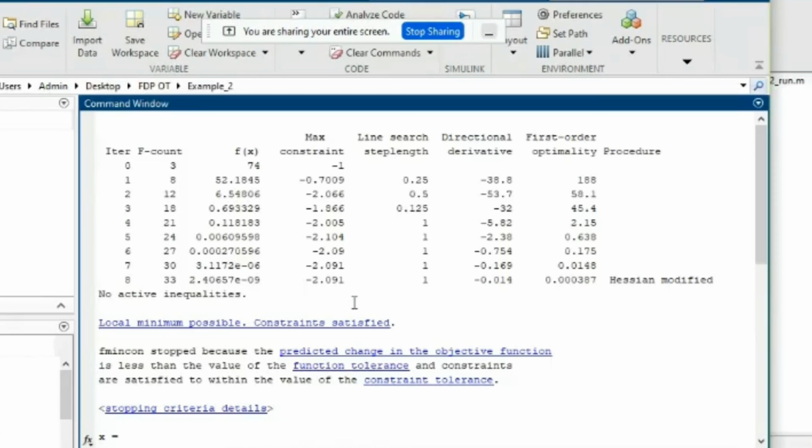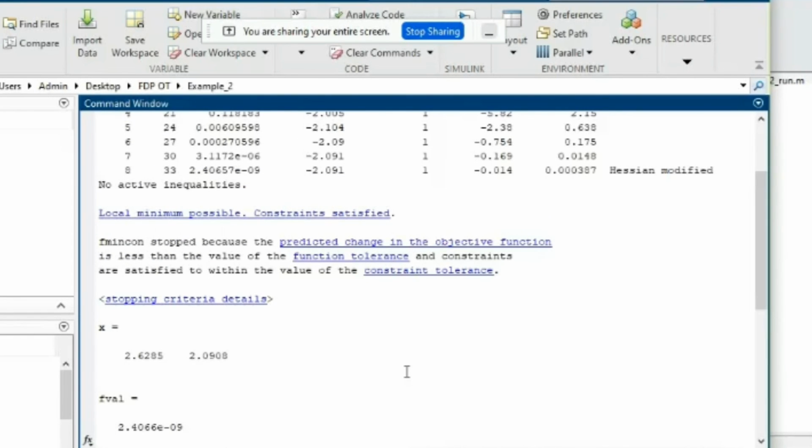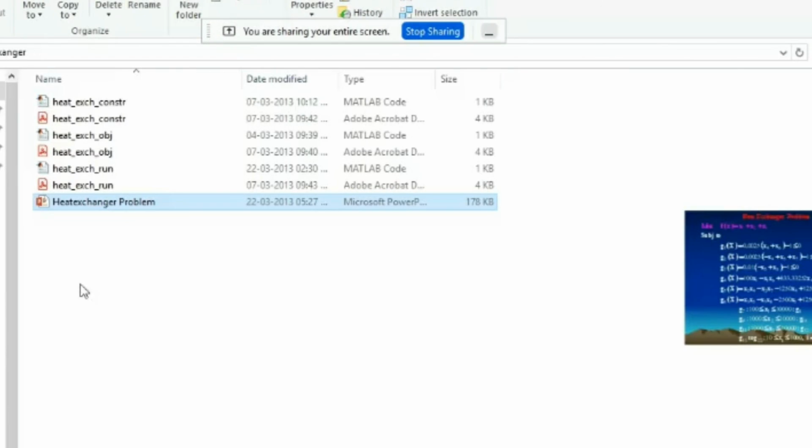Just today morning in the first session, sir was explaining about the genetic algorithm, right? In general, the same problem we can solve using GA, the genetic algorithm. The MATLAB solver is GA. So using the GA solver also we can solve the same problem. I will demonstrate one problem, but regarding the input arguments, it changes slightly. So let me open that file.